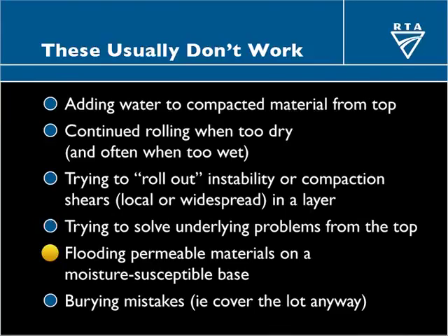If you've got a moisture susceptible material underneath the layer you're trying to compact, flooding water into it is not an appropriate solution. It will get into the underlying material and cause it to become unstable. And finally, burying mistakes. It's often the pragmatic solution, particularly adopted by those who don't have to live with the consequences later on. But the problem always comes back to bite us in the long run. It's not a good idea.